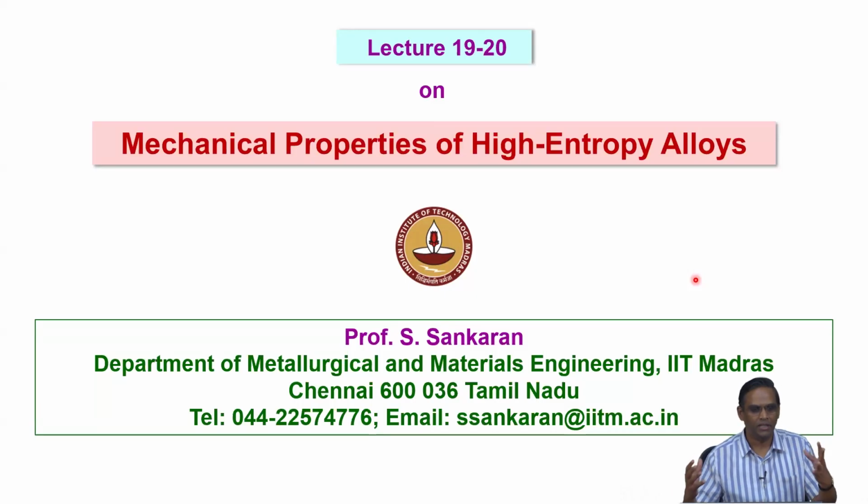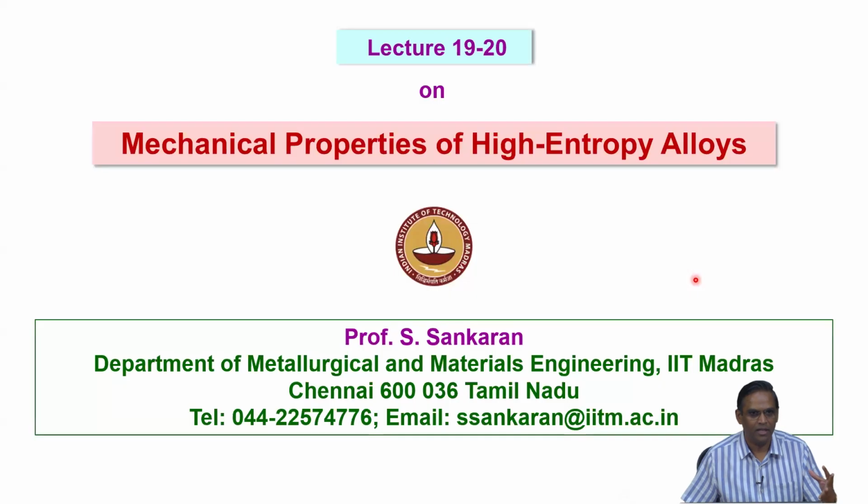If the material has very high stacking fault energy, dislocation movement will be easily permissible, that is, three-dimensional motion of the dislocation structure is easily possible. That means we talk about cross slip, multiple cross slip, and so on, which is easily facilitated.